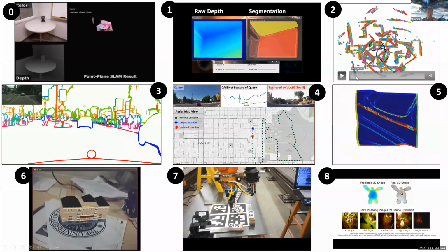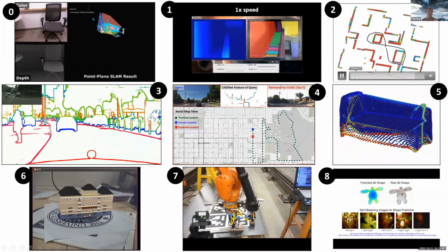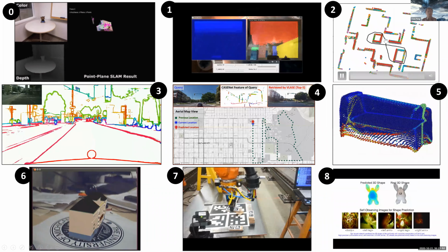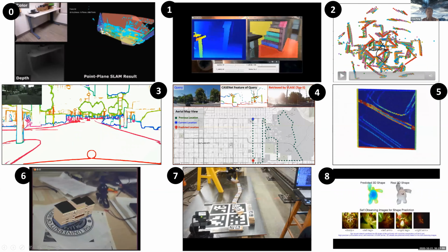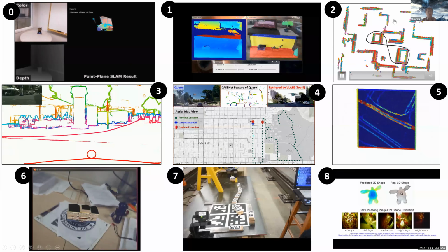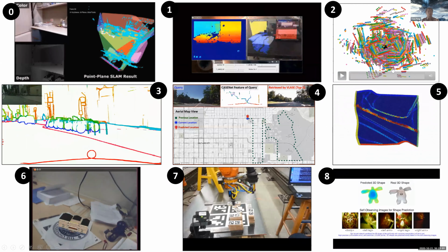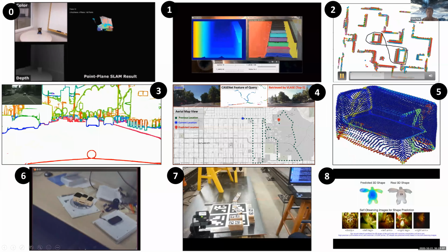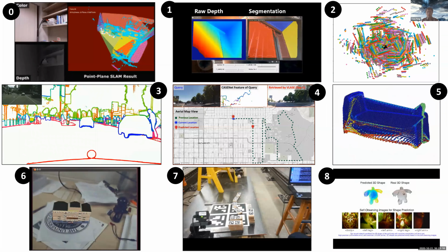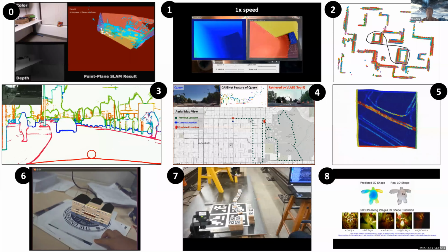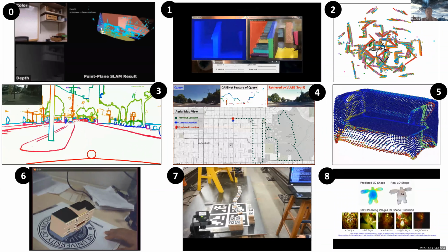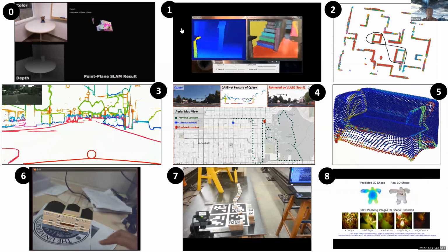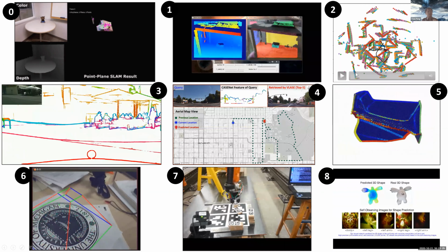One of the ways is to use a LiDAR sensor, which we will also discuss in today's lecture. But the robot is moving. So how do we take the point clouds scanned by the LiDAR at different locations and assemble them back into a global coordinate frame? Usually, this process requires manual tuning or requires people to install some markers, like sphere markers or planar markers in the environment, and then manually work together with the computer to do the registration. This process is called registration.